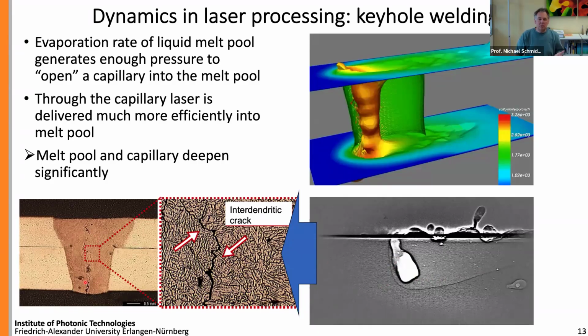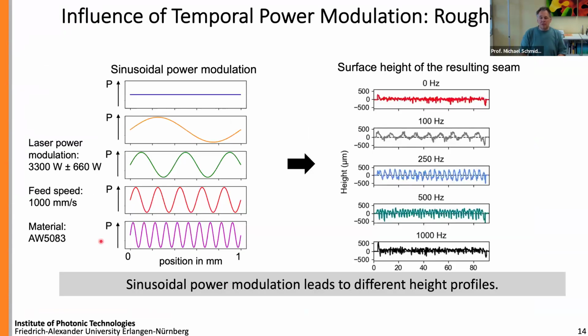So we have a weld seam and maybe we have cracks there, maybe we have pores. And so the relationship between starting there and bringing in energy with a laser beam and resulting here in a good weld seam is much more complex than the example I gave with the ablation, where you just ablate the material very quickly on the spot according to the shape that you had. So we have to take into account the physics of the process much more in depth than with some other processes. Also, this result underlines this.